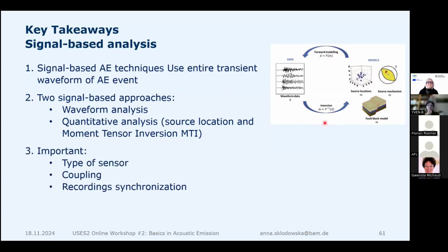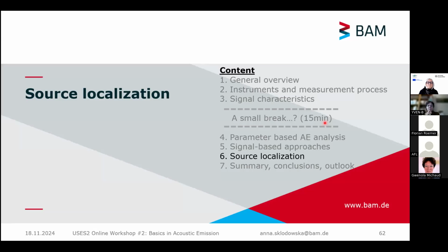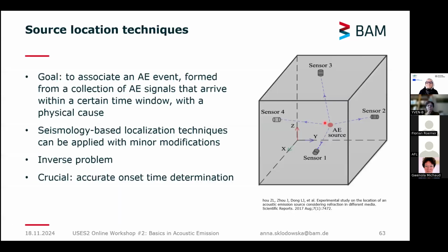It's very important in those analyses, the type of the sensor that we're using, the coupling, and the synchronization of the recordings. And in concrete, with moment tensor inversion, we can characterize cracking in either tensile, shear, or mixed mode. Okay, and coming to the last part of the presentation, I will briefly talk about the source localization methods.